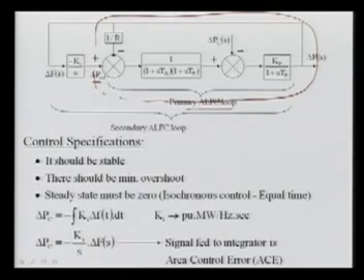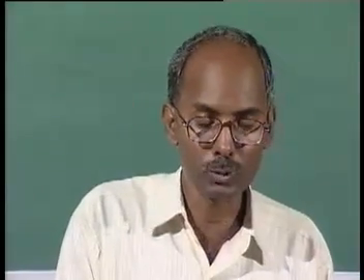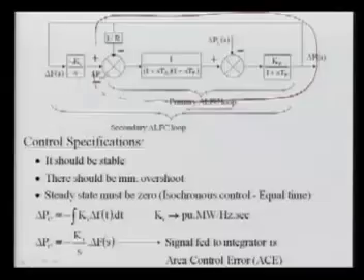Here you can say integral controller. The negative sign here shows that, as you know, when the frequency is negative, we require the P reference to be positive, because when the frequency is less we must increase the power. So the minus term is used. Ki is a gain, and 1 upon s shows that it is the integral type of controller.